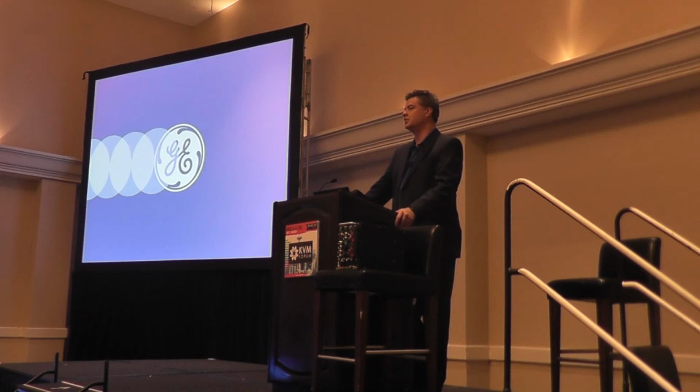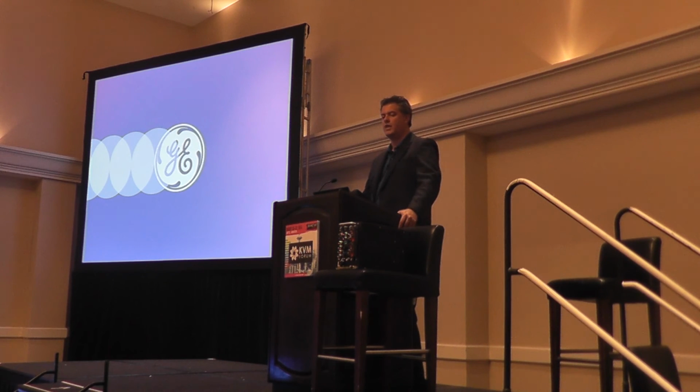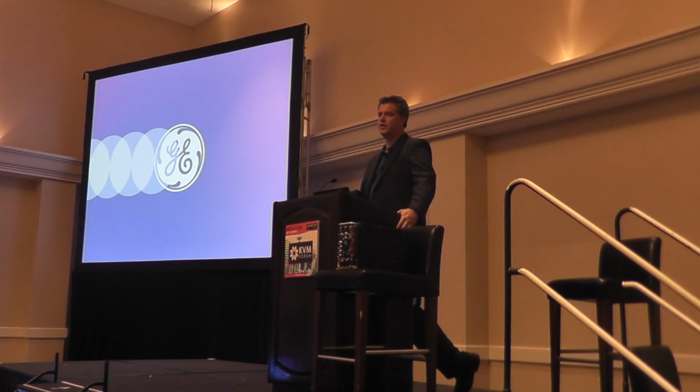But our customers don't like fans because they see them as a maintenance nightmare, cleaning out filters and stuff. Again, these locomotives, when they launched them, they just wanted them to run. We have worked directly with our customers to explain that if you keep things cooler, your equipment will last longer. We're starting those discussions. But for the electronics to date, they've been so used to not having fans that we've spent a lot of time designing processor architectures, heat sink design, and the ruggedness of these things to not require any fans.